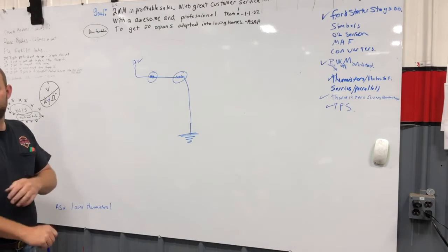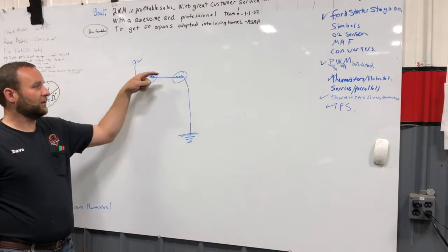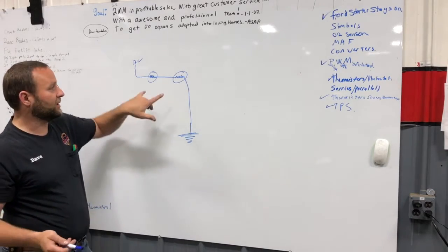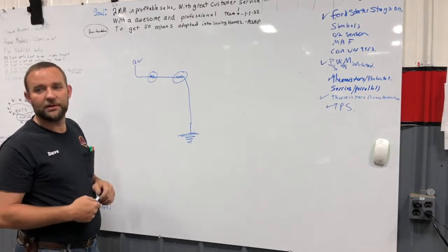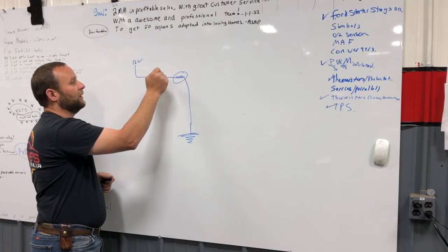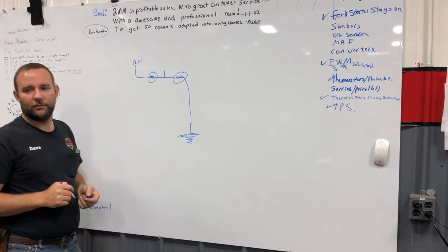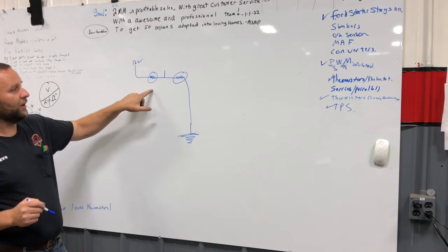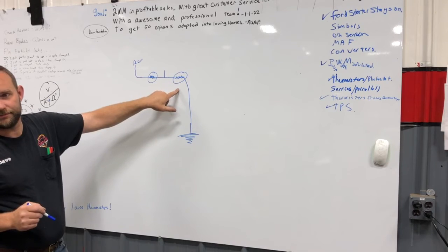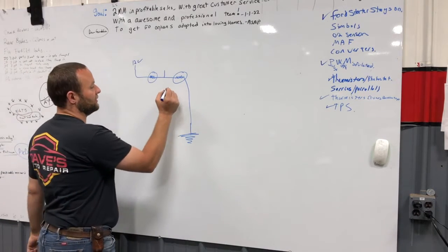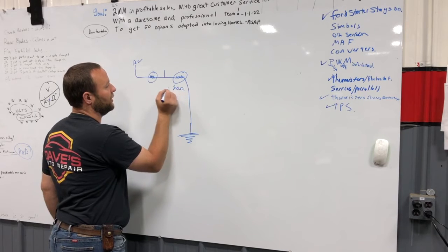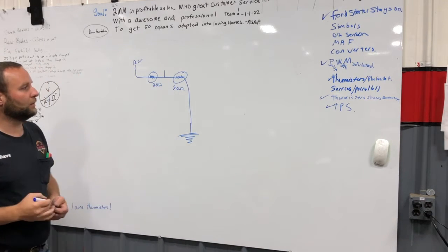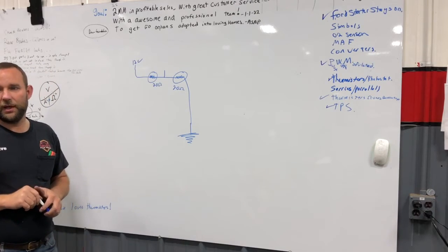Series is all one continuous flow. Continuous flow. Okay, so we have 12 volts here. These are also resistors. Let's say these are both the same light bulbs. What voltage do we have right here? When they're burning, they have the same resistance in them. So let's say this has 20 ohms and 20 ohms. The voltage drop would be 6 volts, half, right? Yep.